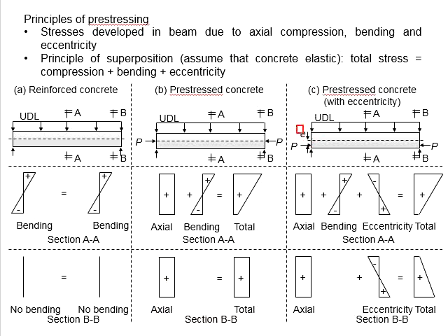It is also noted that the position of the compressive load is also important. If the compressive load is applied on top of the neutral axis, that will give a totally different response in terms of the effect of the eccentricity. Under such circumstances, the diagram of the eccentricity will have to be flipped left and right because the compressive force is above the neutral axis.